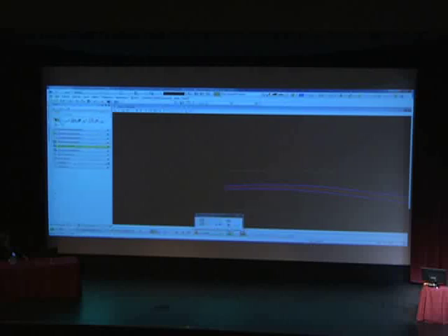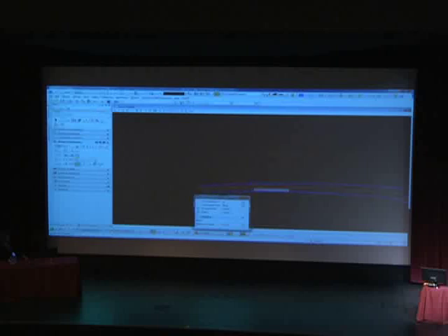So to give it a Z value, I'm going to use a profile by slope. Now, don't go exporting the profile by slope right now, but you could give your edge of pavement a profile by slope. So I'm going to say a 2% cross slope across the road, and it goes ahead and profiles that edge of pavement at 2%. Why are you giving a profile to the edge of pavement? Why are you doing that?